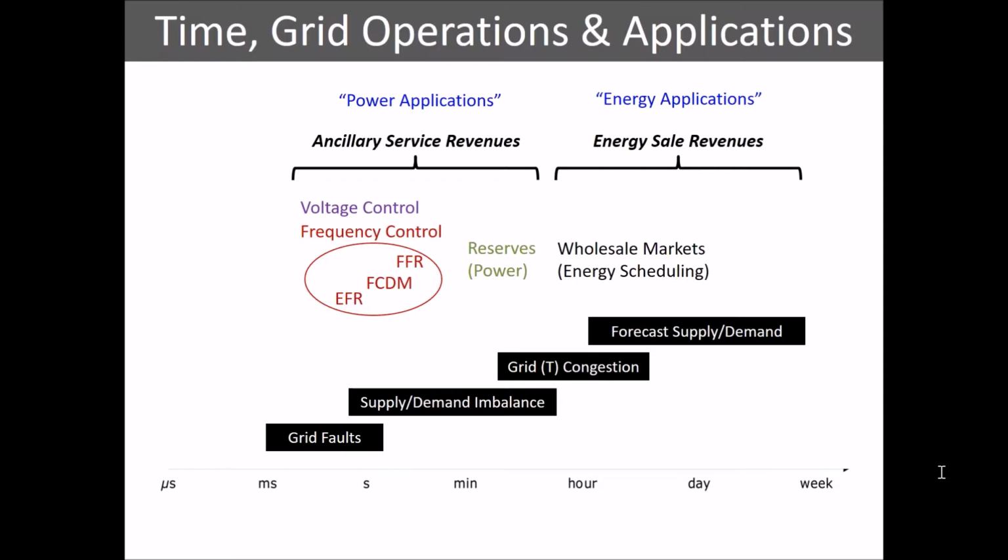Now that frequency has to be maintained at all times across the entire system, and basically frequency varies if there's a difference between the power being pushed into the network and the power being extracted out of it by end users. If you're pushing more power in than is being driven out, the frequency goes up. If you're trying to suck more out as an end user than is being pushed in, the frequency will drop. And system operators have to keep that frequency within very tight tolerances, within very small limits, and they do that because those things can happen on very short time frames by having systems in place, and in particular conventional power plants that can adjust their output very quickly, anything from down at the second, ideally sub-second time frame, up to, for frequency control, tens of seconds.